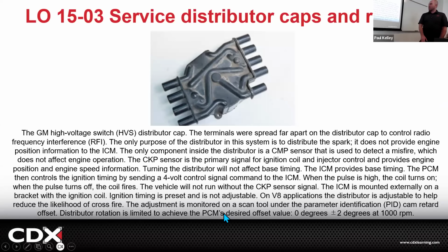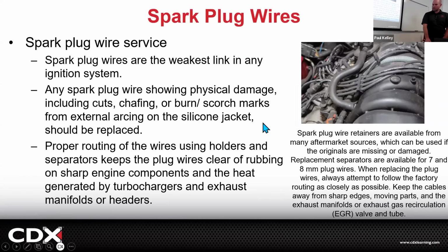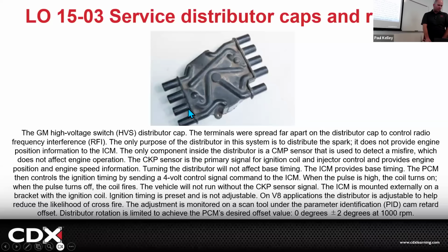And then here's another type of cap. I kind of like these because they're flatter. Sometimes caps in this style come out the side, but back in the beginning, there was one that comes out the top. They're just different styles. It's not a real big deal. If you go to do one of these, it can be hard to tell which spark plug wire goes to which part. So my rule with this is, you go to change this cap, first off, you're probably going to do more than just a cap. But if you're going to pull the distributor out, or you can do just the cap or whatever, you need to mark stuff.